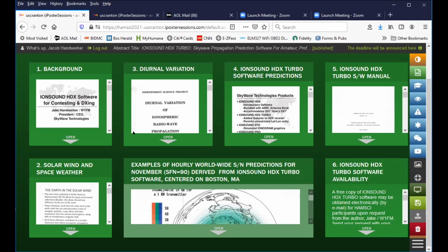This software is intended to produce easy to interpret tabular predictions of RF link performance between any 2 locations on the Earth's surface using transmit and receive location, antenna gain, receiver bandwidth, required signal to noise ratio, transmitter power level, sunspot number or solar flux number, minimum elevation angle from the horizon, prediction frequencies, prediction months, prediction times, and prediction modes involving E and F layer propagation.